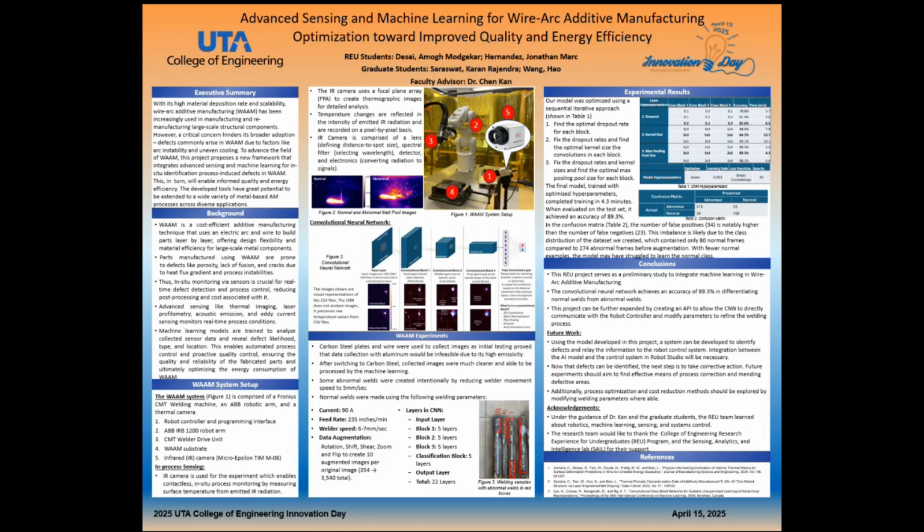Our model is a convolutional neural network trained to detect subtle patterns in these images that indicate weld quality. I'll briefly go over each convolutional block and explain what it does. The first convolutional block focuses on fine-grained features like temperature gradients and small spattering. Block 2 starts to analyze localized patterns such as regularities in specific regions of the weld. Block 3 looks at overall heat structure, identifying whether the heat is sharply concentrated or more spread out.